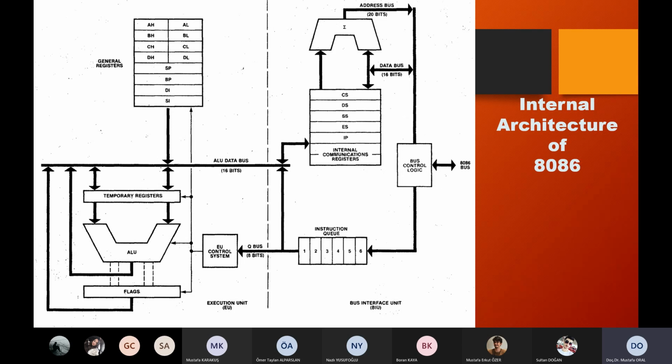And as in the case of the increment AL example, after reading the increment AL opcode, it understands that it has to increase the content of the AL register. So it starts an operation, getting the content of AL into the arithmetic logic unit and providing a pseudo 1 at the second input. The first input will be the AL register and the pseudo 1 will be here, so it will add up and the results will be stored in AL.